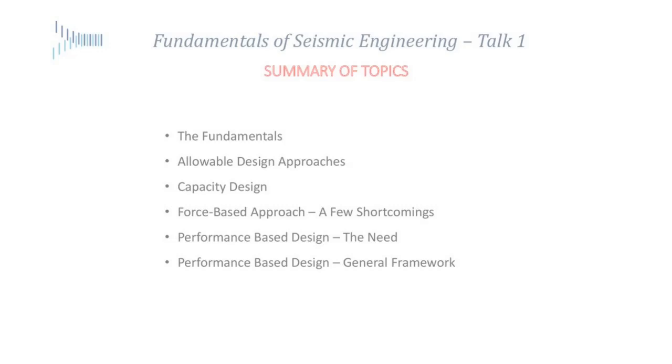So today we'll talk about the fundamentals. We are going to talk about some of the allowable design approaches. We've been using the force-based design for quite some time. Now the codes are moving away from it, and the performance-based design is coming in to the picture quite fast. The Canadian Highway Bridge Design Code is one of the first ones that's fully incorporated performance-based design. One of the basic tenets of seismic engineering is capacity design, which I will talk about.